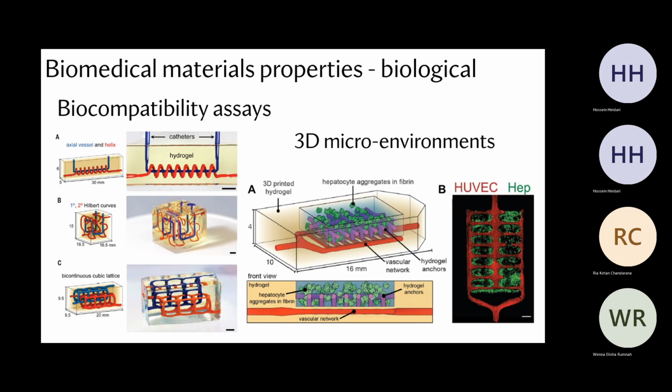When I explained it, you didn't do it in person to play around with the knobs, but what was one of the important factors that determined the print time? The number, yeah, exactly. How many layers you have. And then, apart from that, the time you spend per layer. The exposure time. How long do you expose? If we have super long exposures, you're going to have full conversion. If we have shorter exposures, you can barely get the geometry. If you have too short, if it's undercured, it can fall apart.